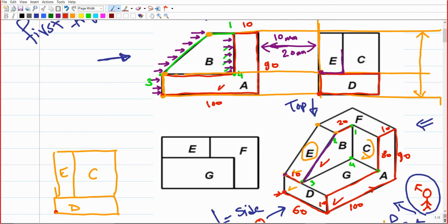So if you try to project it into this direction, you're gonna set up a 90 degree triangular shape, right? So the projection of this line will be seen from this side with this height, but it will be seen from the top view with this length. But from the front view, it will be with the exact length.